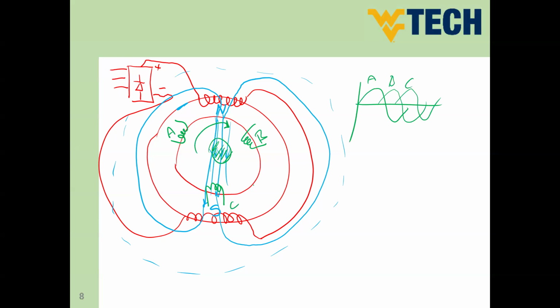So the output of these windings now, guys, is three-phase AC. This three-phase AC will be converted now to DC by means of the rotating rectifier. So if you can imagine with me now, this is our shaft. We have here the exciter stator, which is supplied by our rectifier circuit from the three-phase AC.